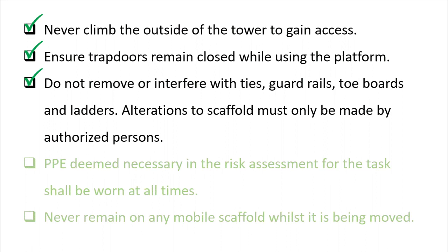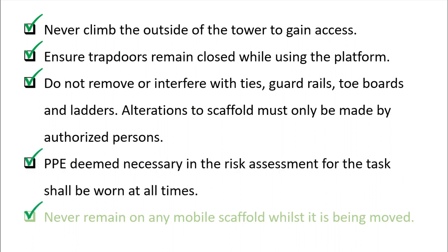If you are frequently moving from one place to another place, you need to have a full-time standby authorized person to alter your scaffold to make sure that it is suitable for your job. PPE deemed necessary in the risk assessment for the task shall be worn at all times. Never remain on the mobile scaffold while it is being moved.